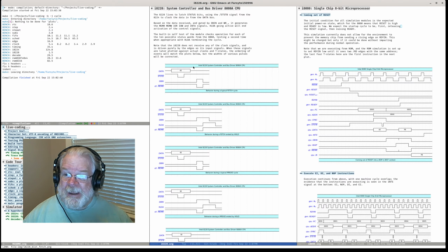where I'm showing the behavior of the 8228, and I'm saying, well, I have an incoming data bus with this value here, and this says that during a fetch cycle, this is driven into the chip, so we are recognizing the status strobe says, look at the data, and A2 is the thing. And this confirms that for a sync cycle with status strobe hitting us with A2, when DBIN goes up, we will be asserting the MEMR signal low. With A2, there's our data.